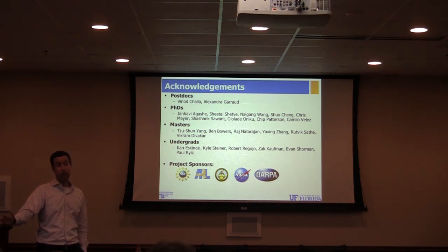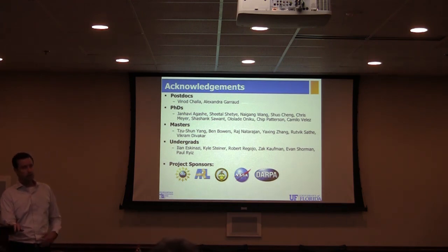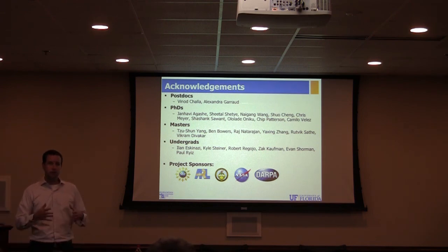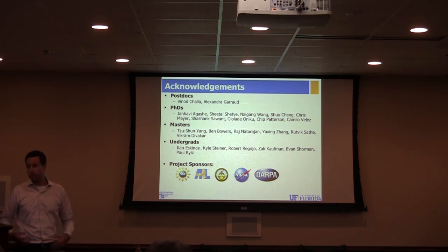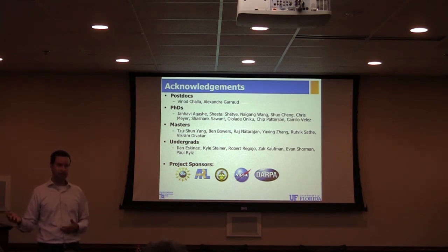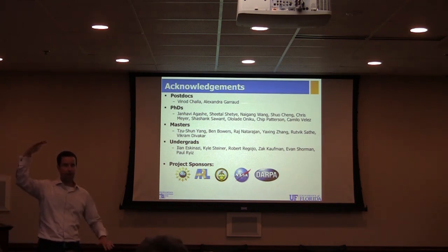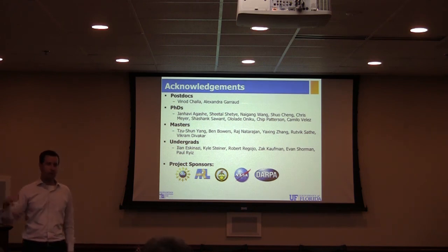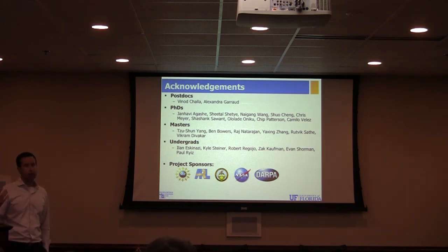It is very cool technology, and it's one of those things I feel has been a little bit oversold. People hear energy harvesting, and the first thing they think is I'm going to walk around and keep my cell phone charged. And the gap between that and what we can actually harvest is orders of magnitude difference. So low power wireless sensors, these kinds of things are possible. But the main thing with energy harvesters is they're power limited. So if you need big power, you need a big harvester. And people don't want a big harvester, they want a little harvester and big power. So there are just a lot of trade-offs.